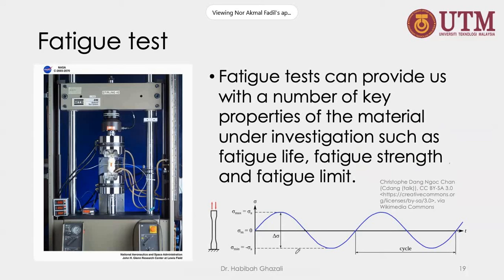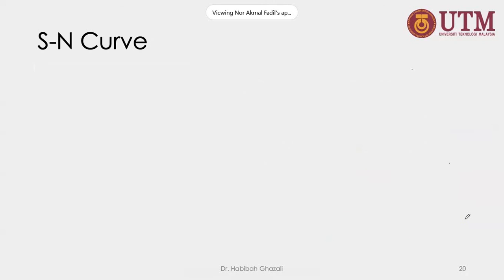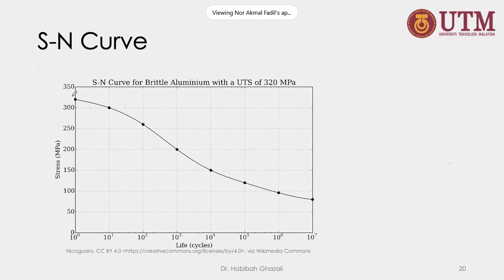You pull and you release the load, pull and release. These are the maximum loads that you give, and this is the initial mean with the load. This is tensile and this is compression load. Give on and off, tensile and compression, tensile and compression. After several cycles, it will fail. Then we plot like this.